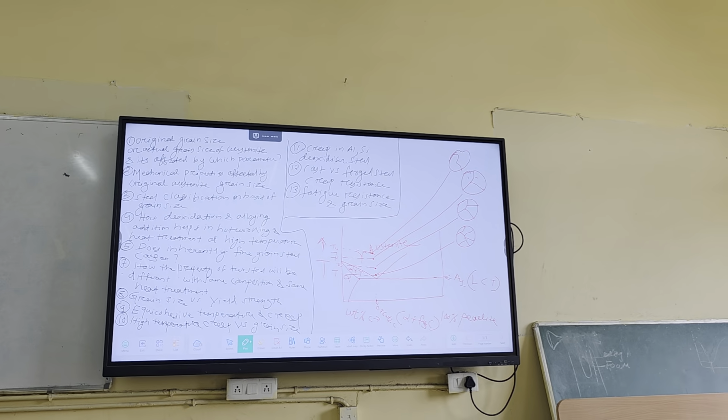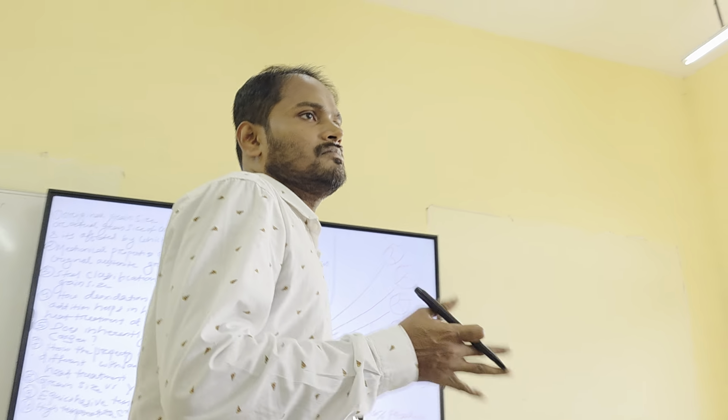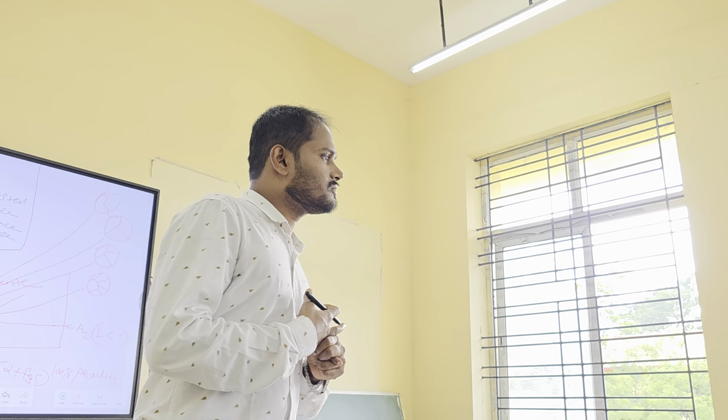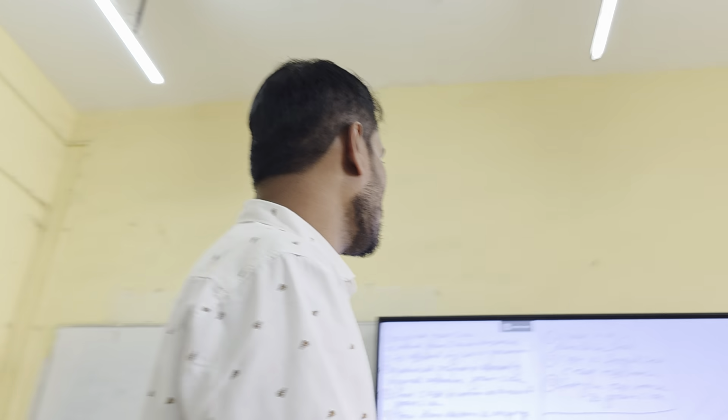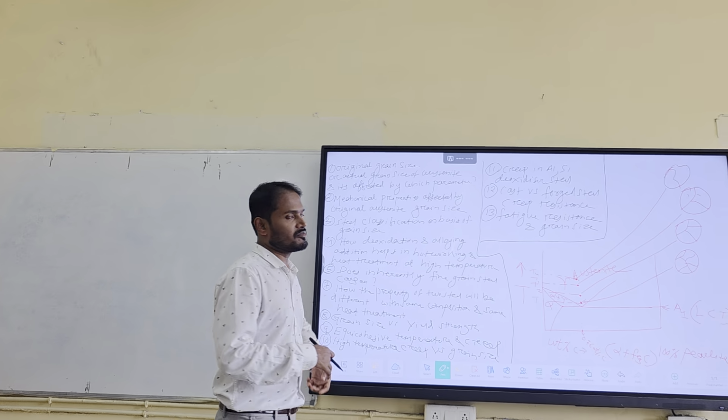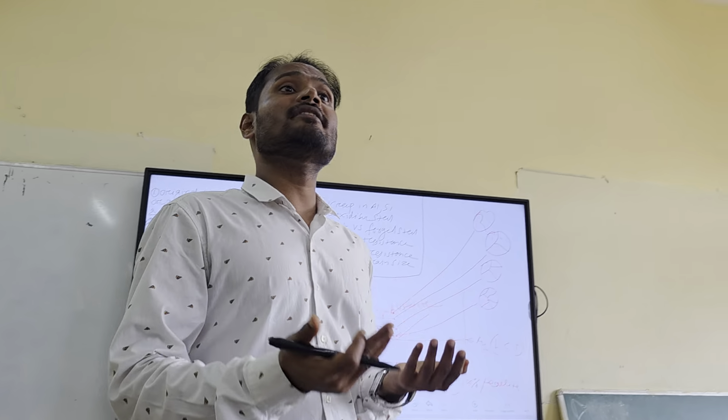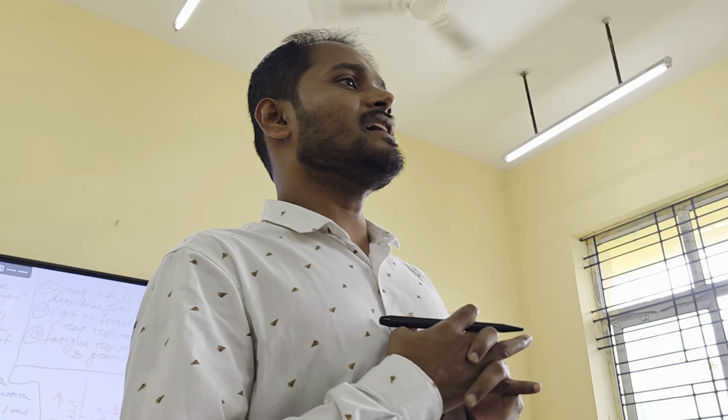And that size is actually called actual grain size, or you can also call it original grain size, or actual grain size of the austenite. Okay. It is very simple. Just room temperature phase, you are converting into austenite, and the size of the austenite grain is called original grain size of the austenite, or original grain size of the steel sometimes. Why are they saying this? This is the original grain size of the steel, because that grain size will affect your final